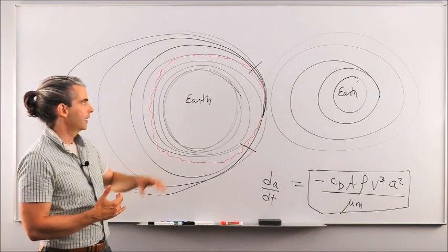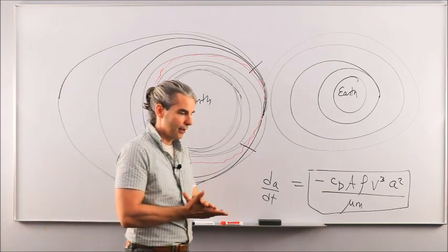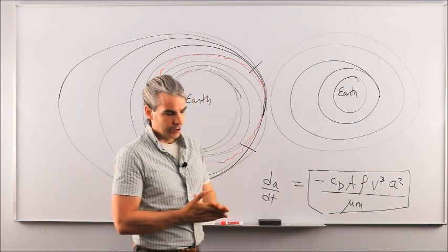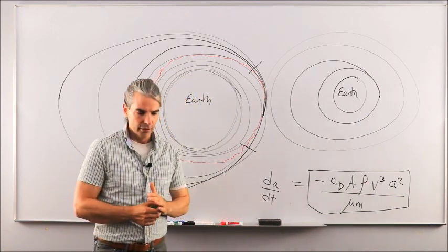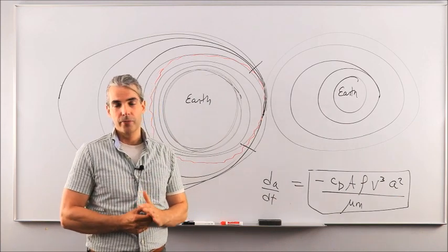And specifically here, we did some more detailed work on the effects of J2, creating a time variation of our RAAN and a time variation in our argument of perigee.